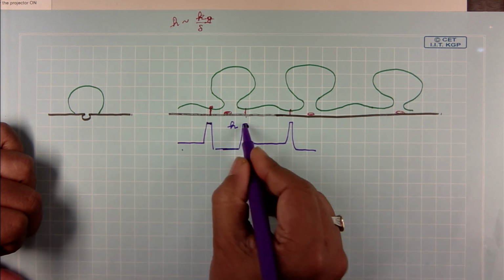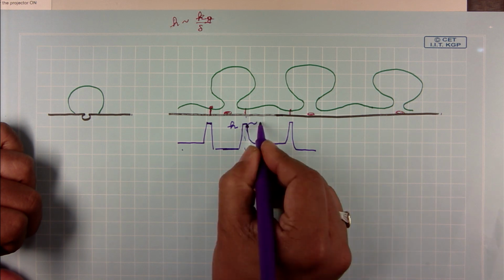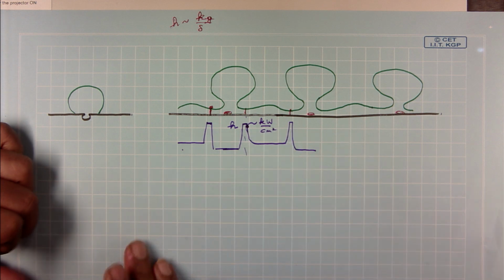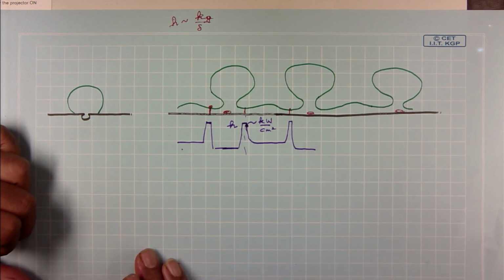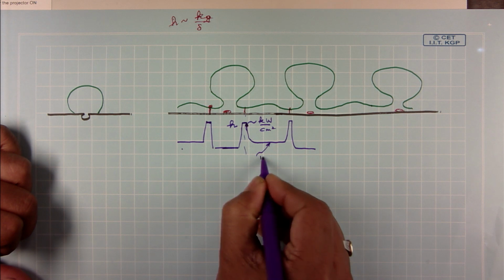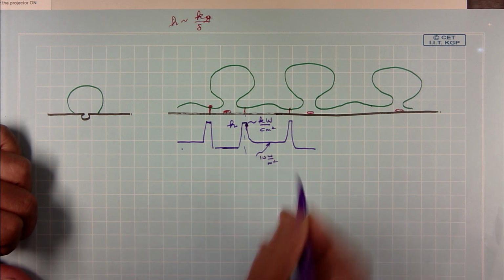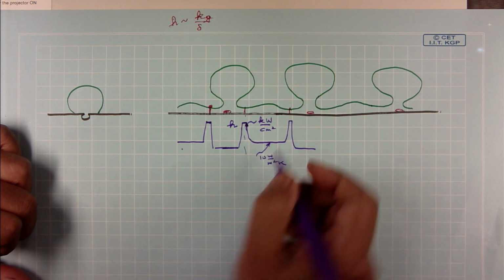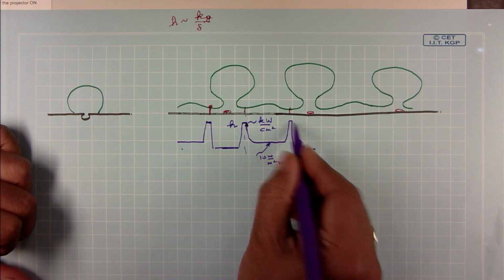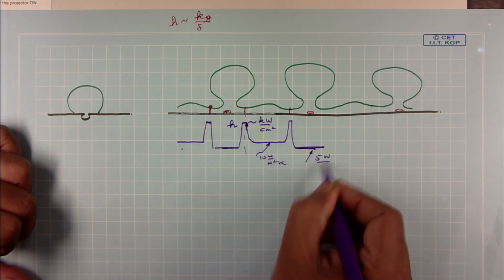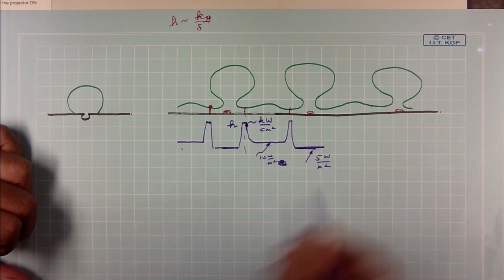It turns out this peak heat transfer is of the order of kilowatts per centimeter square at these locations, whereas over here you are looking at something like maybe about 10 watts per meter square Kelvin. And over here you are looking at very low values, something like 5 watts. I mean, I am talking about the heat transfer, not the heat transfer coefficient, I am sorry.